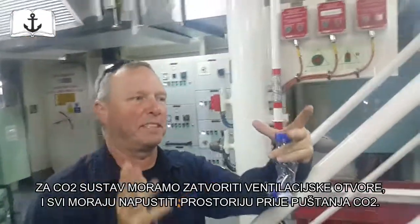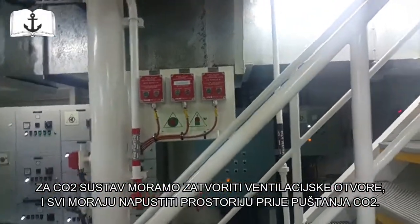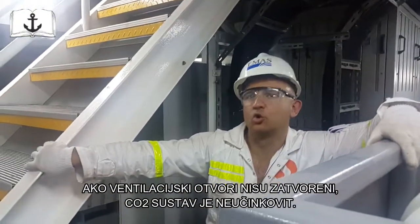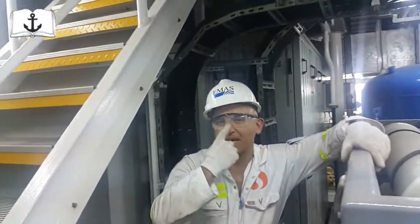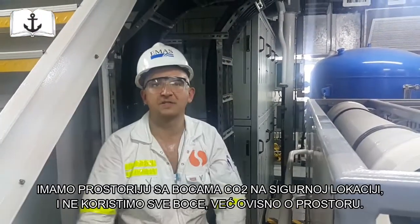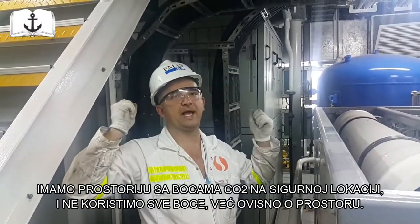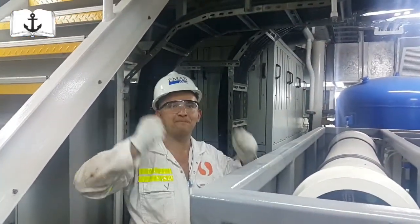You would need containment with CO2. You're going to need containment to be effective. Otherwise your CO2 will go out. This one you can activate and it will extinguish the fire, but with CO2, if you don't seal off everything, you're losing the efficiency, because you need to get rid of air and pump in CO2. Another thing is that the regulation says you must have a lot of cylinders. For example, we have a room with the big bottles, like welding gas bottles. For this room you don't need to launch everything, I think 4 or 6 bottles can be enough. You have spare ones, so it will keep pumping.